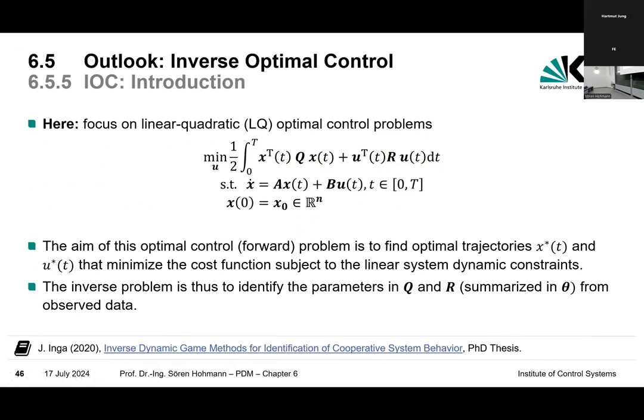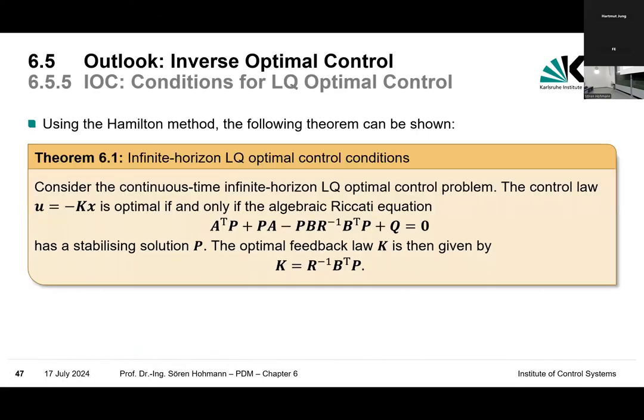And, well, you know everything for that. Remember, the optimal control problem is solved by means of the Riccati equation. So any solution of the quadratic optimal control problem has to fulfill the Riccati equation. And if you remember the Riccati equation, well, there's a zero. And now the question appears: if I tune the parameters some way, is it possible to achieve zero there? So let's have a look at that.